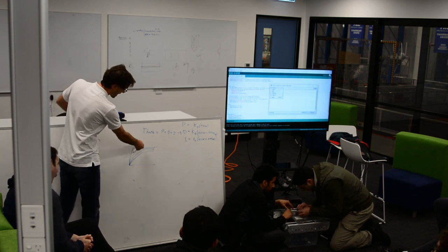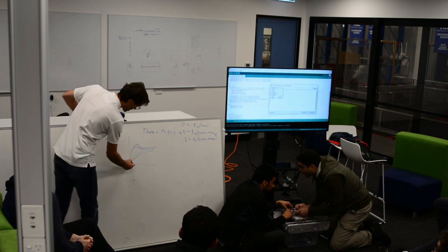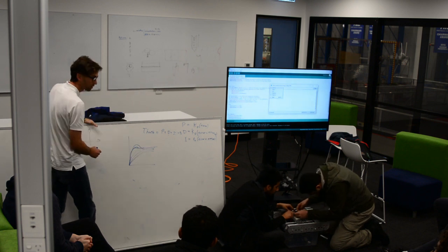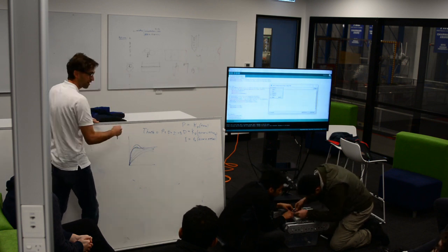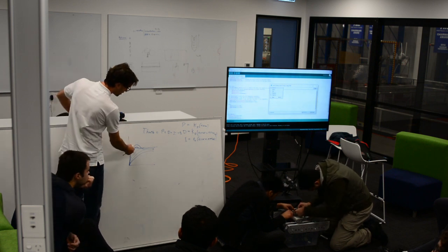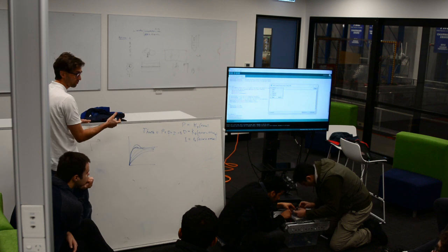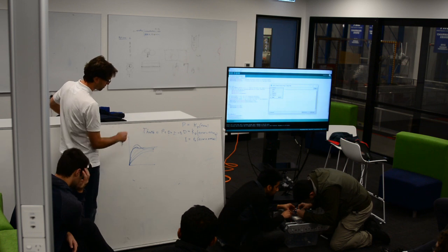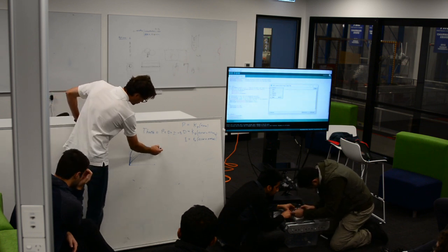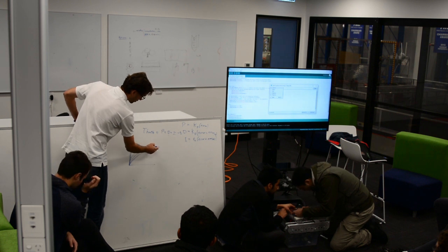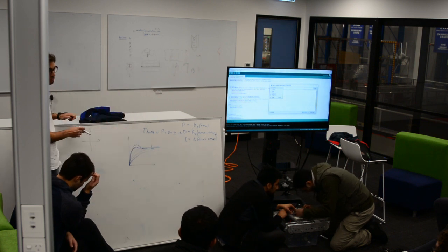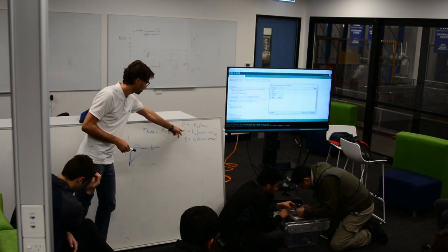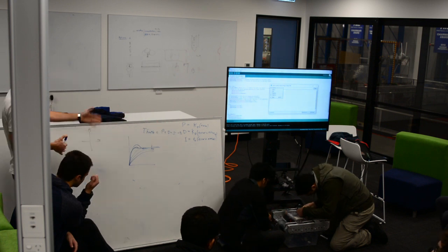Then once you get that, you add D in. And the D will slow you down as you approach, so that you'll still come up hard, but you'll slow down as you come in. So the D term will allow you to get there, just like you have a really hard, stiff proportional control, but it'll prevent the overshoot, because it'll start to shut off the throttle before you arrive, which the P term doesn't do a very good job of. So the D might be useful, and then you may or may not need integral control. It doesn't look like we need it, because our steady state errors look like they're really small. But you can still try some of it, but it's generally simpler not to. You can have P plus D or P plus I, depending on the situation, and in some situations you don't.